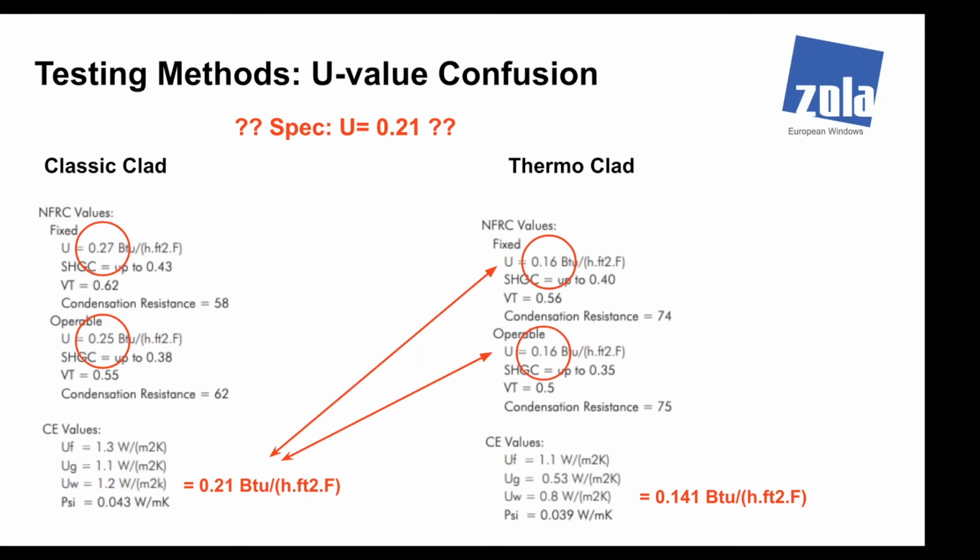Energy code, of course, calls for, since you were on the solar heat gain coefficient, what is it now? It had been 0.4. I can't remember what it is for the new energy code. I think they've dropped it to another 0.38. We're seeing a lot of 0.38. Maybe that's what it is. I suppose if one were to do a full ASHRAE 90.1 analysis, you could use higher solar heat gain coefficients and still meet the code.